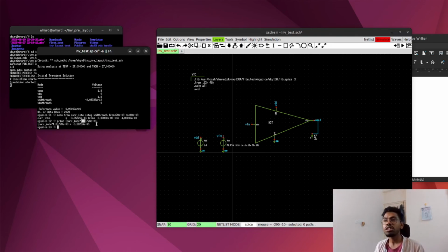So in summary, mostly we have three ideas to reduce the power consumption. One is architectural changes, reducing the switching activity to reduce the power consumption. Another is to reduce the CL; try to do your layout efficiently, because in CL we also have a component which is coming from the wire. Here is an inverter, there is another inverter. How you connect these two? If you use a long path, then there will be more capacitance and more power consumption, so you can reduce that too. And third would be to reduce the voltage, right?